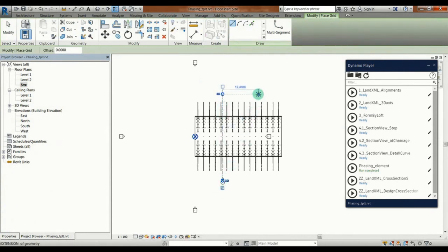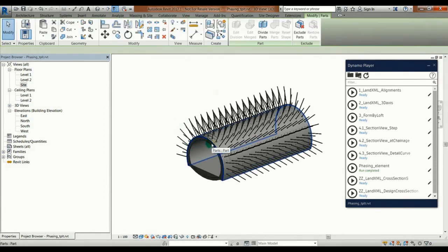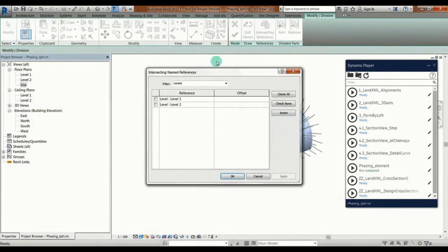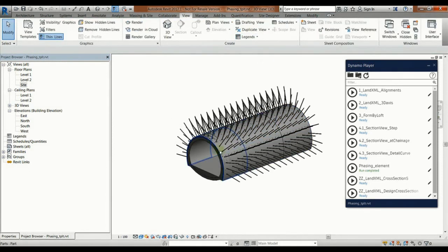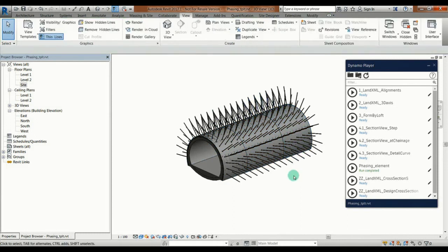Then I can also cut those parts because I'm not going to excavate for 30 meters long. So I just select for instance the shotcrete layer, intersect. I will just hit the grids here. Hit OK, and then done. Revit just split this solid in 3 parts, and then I can assign for each solid a phase.